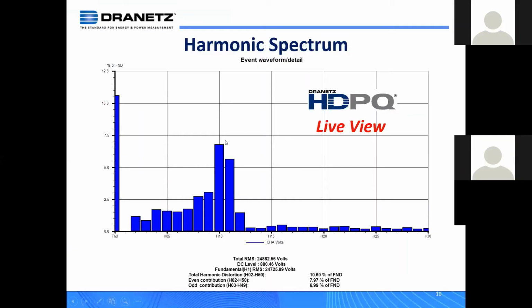Okay, so you'll see pictures like this from the instrument. This is very easy to describe here because it's much larger here. But what you'll usually see is each individual harmonic. This is the second harmonic, the third harmonic, the fourth, the fifth. Usually this is displayed as a percent of the fundamental. So what you're seeing here is the harmonics are displayed as a percent of what it should be. The fundamental, you want 100% in the fundamental. That means you don't have harmonics. You have a pure sine wave. That's the ideal. We know that's not really reality in what we do.